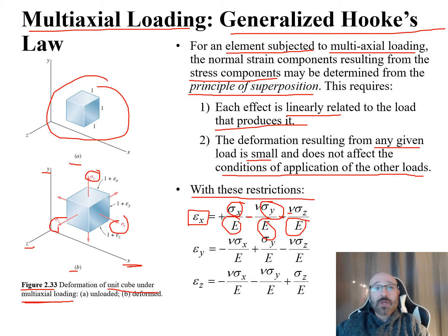So we have similar relationships, so that we see the correspondence. We're talking about our epsilon y. You can see the y direction here is going to be the positive one without our Poisson's ratio, and the same with the z direction for epsilon z. That's just our sigma z over E. The other ones are both going to be negative in the other two directions times Poisson's ratio.